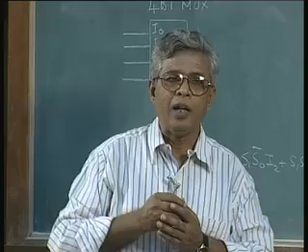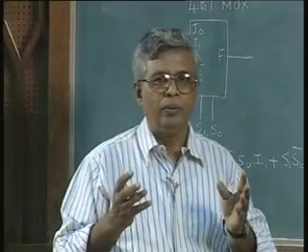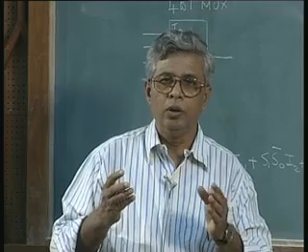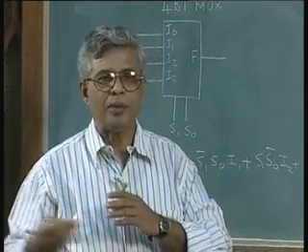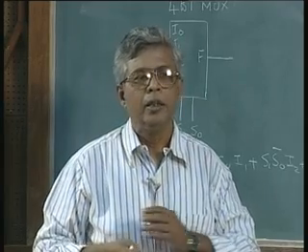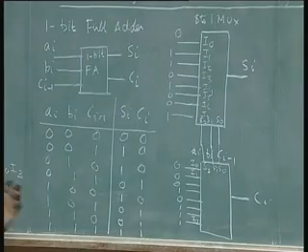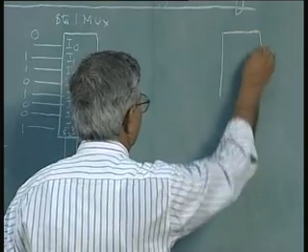Like in the Karnaugh map case, if you are given a free ride, you would use AND gates, OR gates, inverters. But if the person says use only NAND gates, we will do some further manipulation. The same concept here, I am going to use 2 4 to 1 multiplexers.